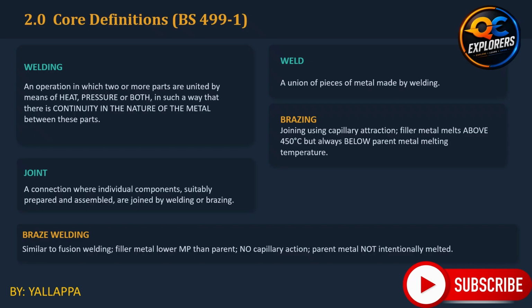In braze welding, the filler metal again has a lower melting temperature than the parent material, but the process does not rely on capillary action, and the parent metal is not intentionally melted in the manner of fusion welding.